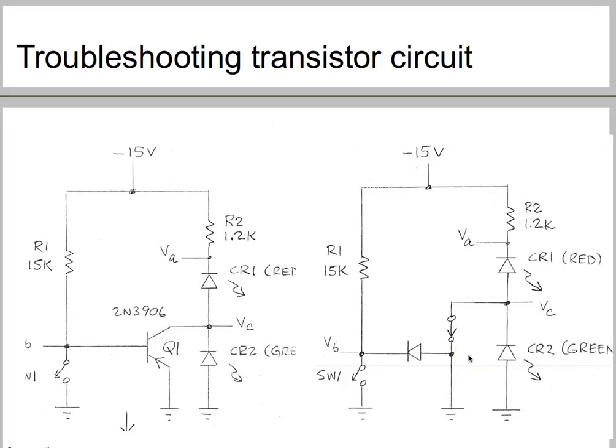For example, a 2N3904 transistor. A transistor and diode data book or the data sheet will tell you whether the transistor is germanium or silicon, and whether it is NPN or PNP. Its typical use, power amplification, switching, etc. Its current gain, upper cutoff frequency, breakdown voltage, power rating, and much more information you can find in the data sheet.